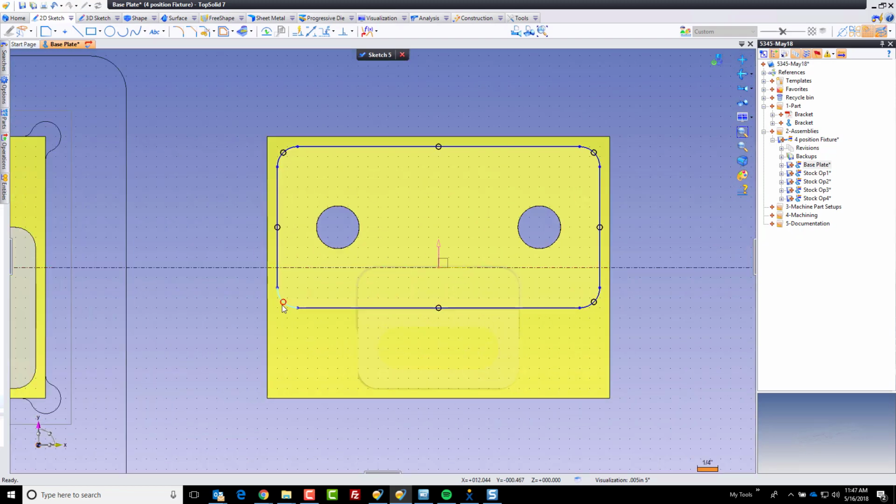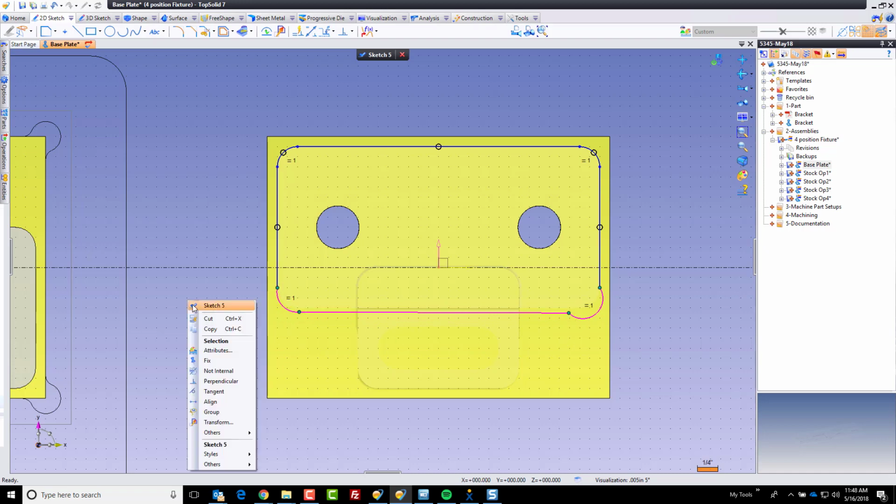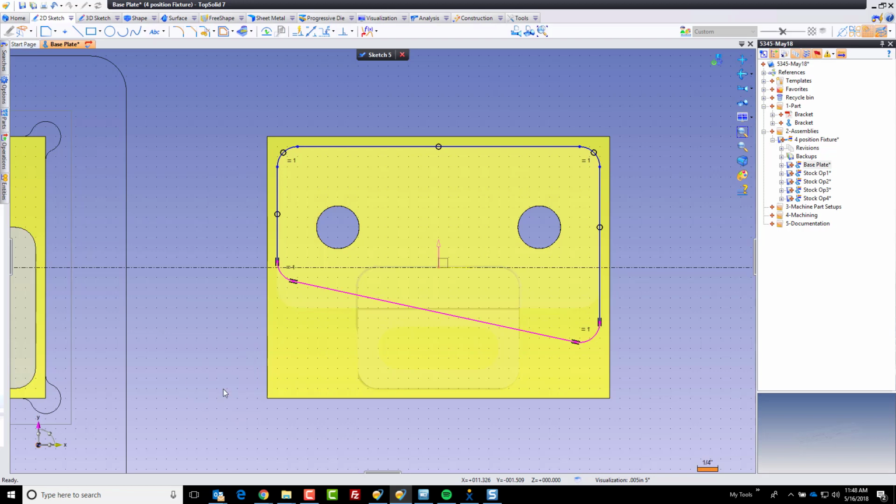So these little black circles, they are telling the software to be coincident with the edges they were projected from, right? Now, since I don't want to maintain those coincident relationships anymore, I'm going to build some new relationships. I'm going to make those equal to each other, and now by doing that I should be able to drag this thing around. But I've noticed that the tangency is lost. Ah, that's too bad. Well, I'm just going to hold Control down, Windows select each of these points, right click again, and just force them to be tangent.